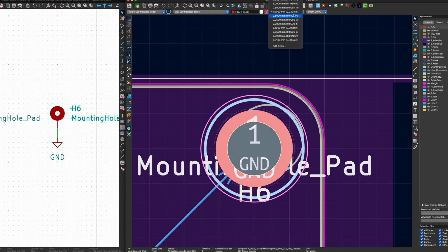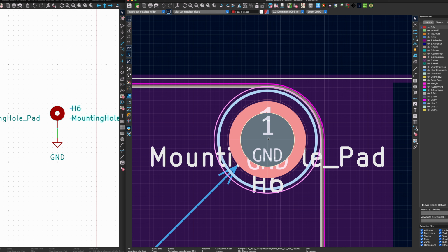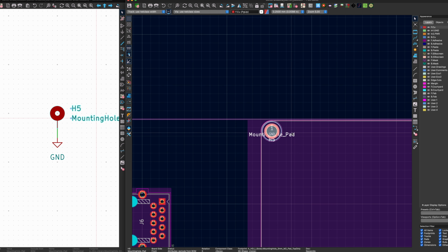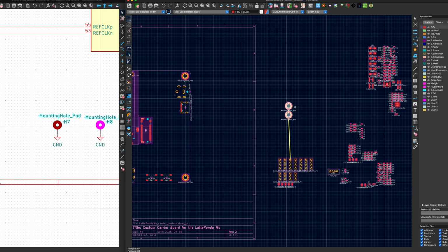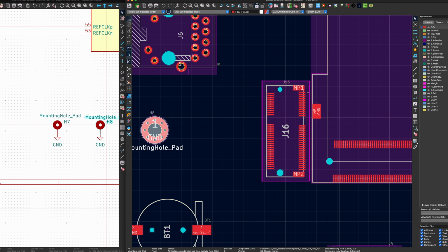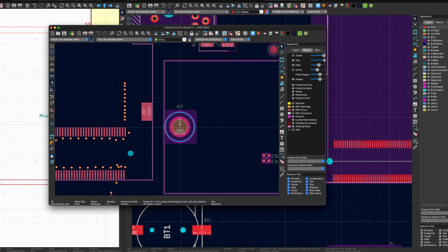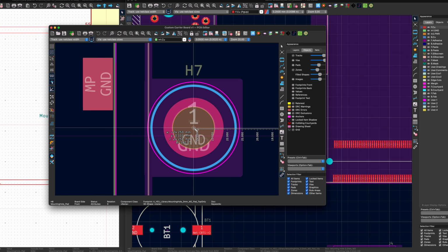By the end of this course, you'll have the complete workflow from schematic to final layout of a professional high-speed carrier board. And more importantly, you'll understand why each decision matters: why differential pairs must be matched, why ground planes must be continuous, and why documentation and verification are essential in high-speed design.